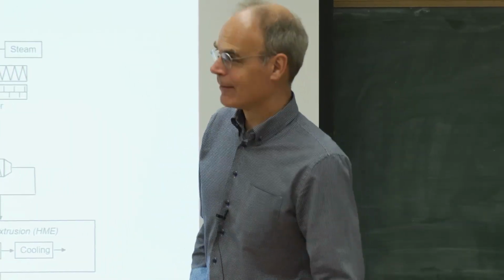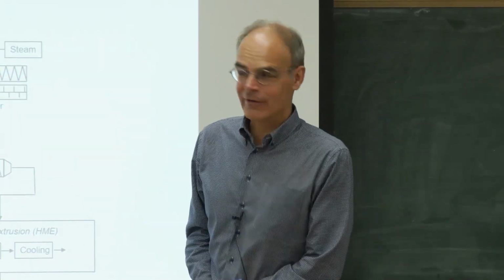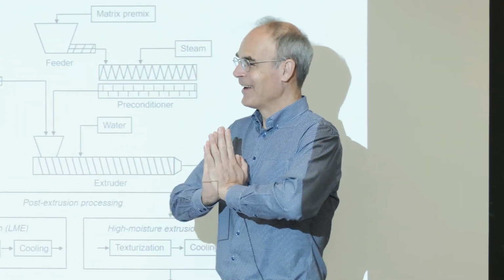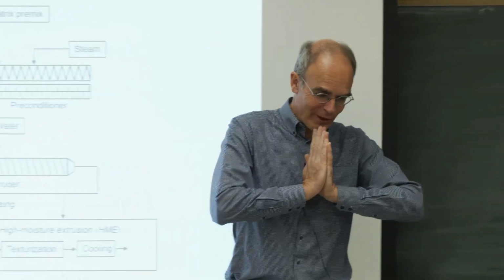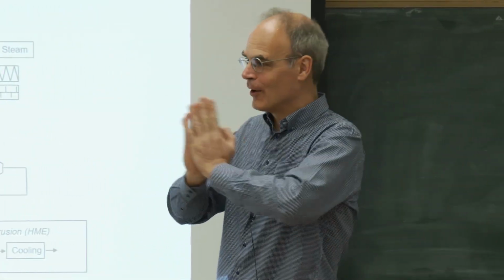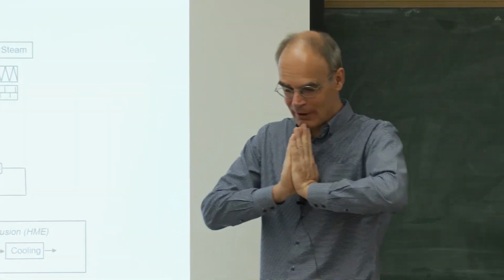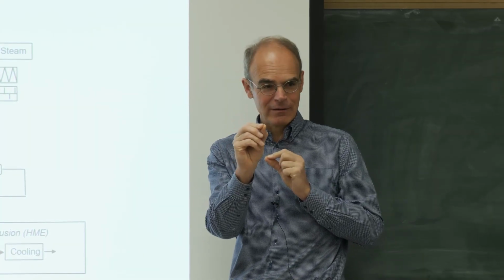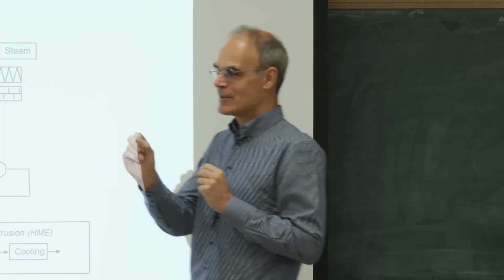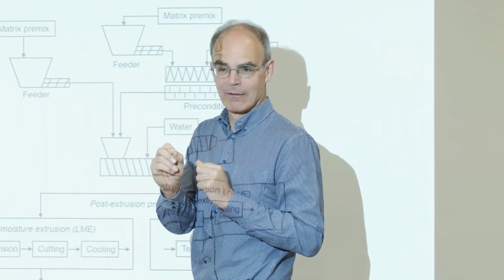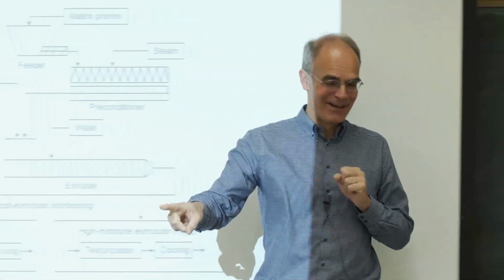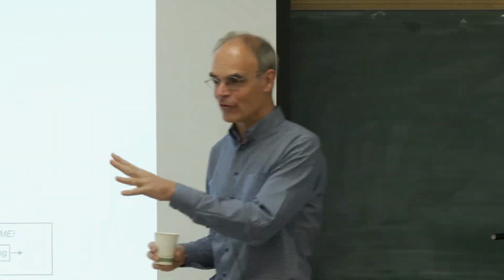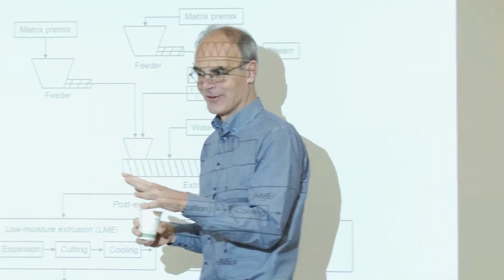I must say, it was challenging. But we love challenges. Yeah, so we really have to look at how the viscosity builds up. A long story short, you have to really carefully look at how the extruder builds up to make sure the egg sets exactly at the die. Because what happens if the egg sets in the extruder barrel? What are you making? Scrambled eggs. Scrambled eggs, exactly. So yes, the extruder could be a really good technology to make scrambled eggs, but it's probably the most expensive way to make scrambled eggs.